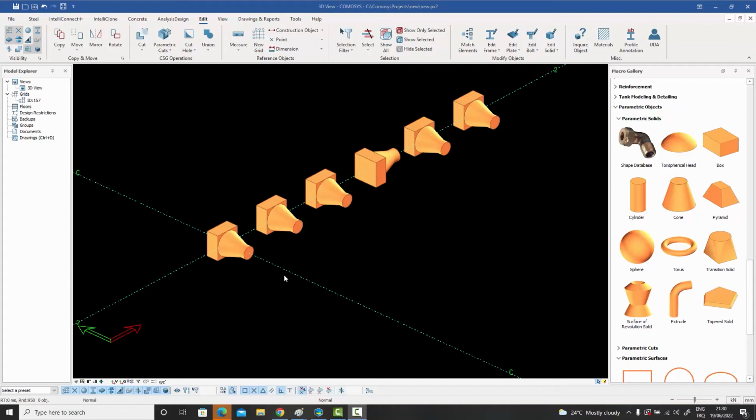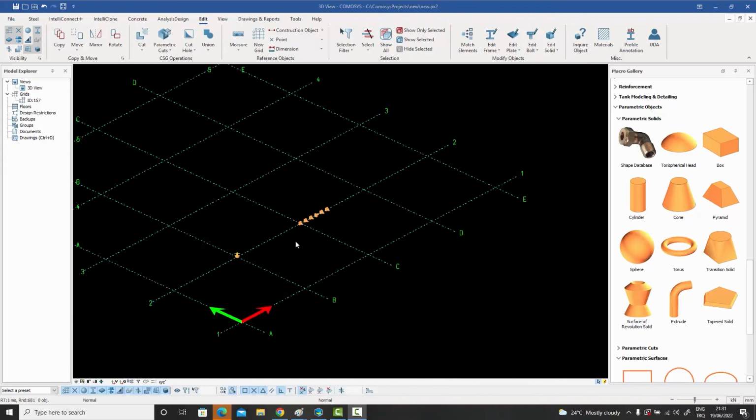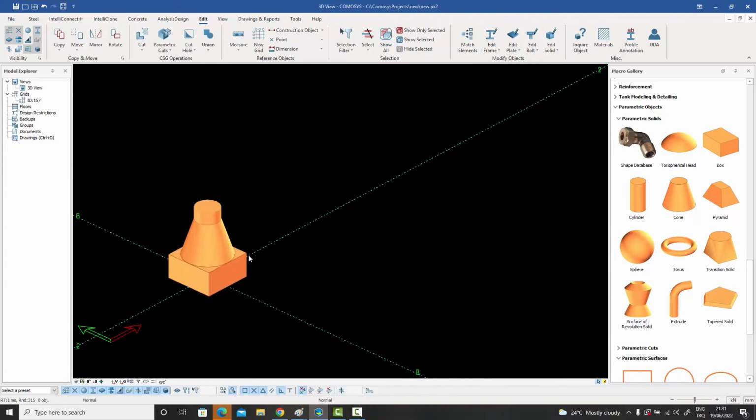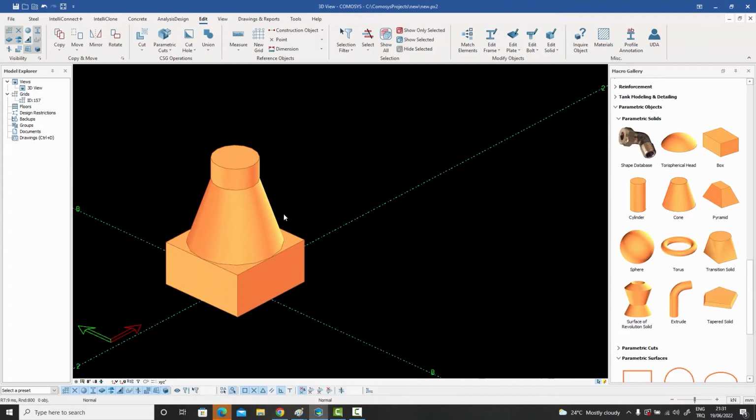Let's say we have created this basic shape and we've used it extensively in the model. Let's say we've used it in hundreds of different locations in the model, thousands of different locations. But then something comes up and we realize that we had entered the shape either incorrectly or there's been some modification in the basic shape of this coupler, which we didn't know, or whatever this item is. Well, what we can do is we can redefine the shape. So let me go back to this definition area.